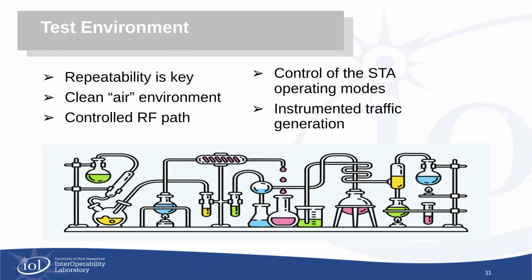It does also talk a little bit about the requirements and the configuration of the device under test, and the device under test being unmodified in its deployment configuration. So we're not looking at a cabled RF environment. We're not looking at disabling certain parts of the device or disabling certain radios, right? So that does couple into the testing. And then it also does address some things like how the device is configured in terms of what RF path or RF channels are being used for each of the wireless technologies.